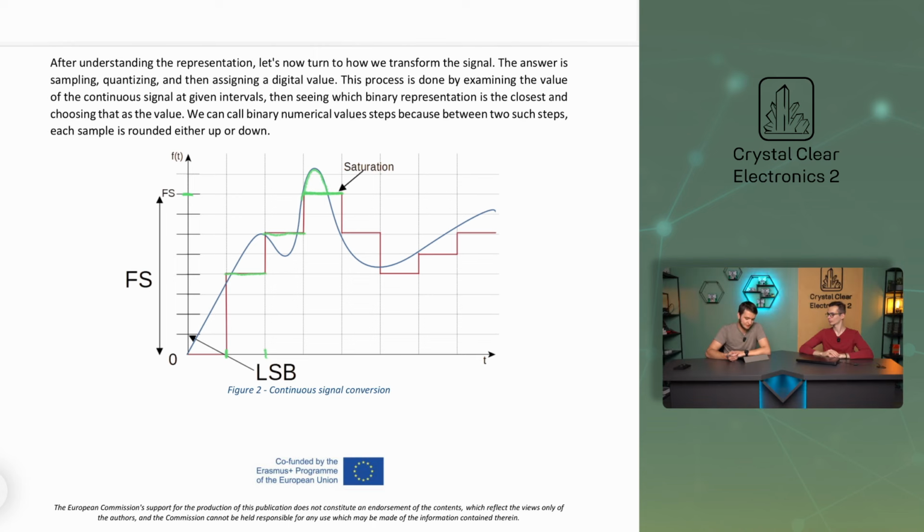Unfortunately, it's also easy to see that the samples taken from the continuous signal do not describe the original signal correctly. This is, of course, a nuanced expression, since it's always up to the designer to determine the error below which the original signal is considered correct. In the present case, the conversion is not shape-preserving, since the signal changes faster than we sample it. Luckily, there is a solution to this problem. To improve this, we need to sample the signal more often, that is, increase the frequency of our sampling, so that we can describe the input signal more accurately.